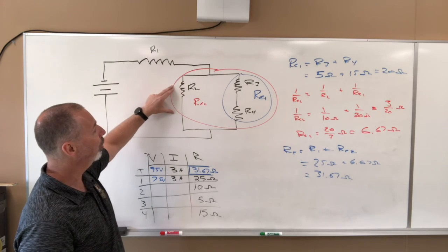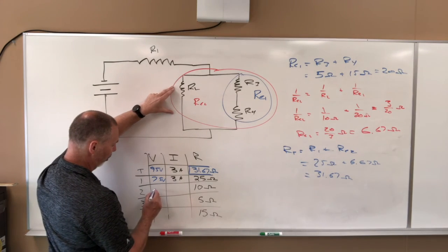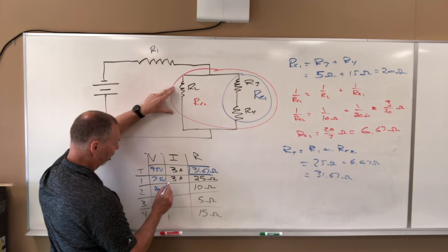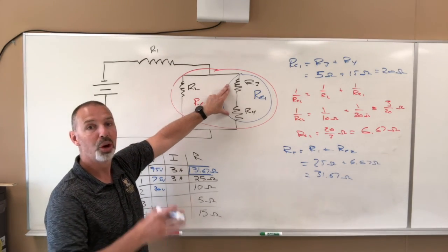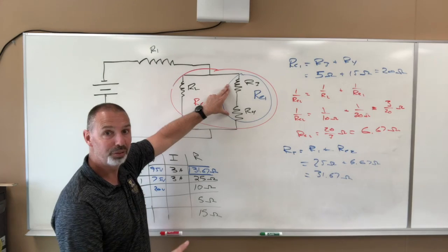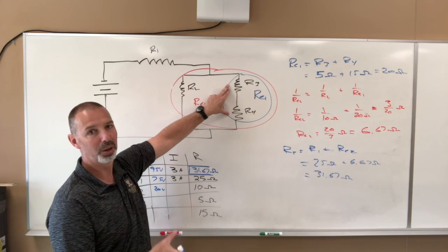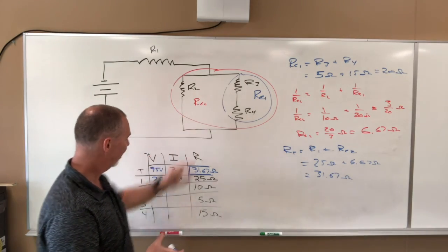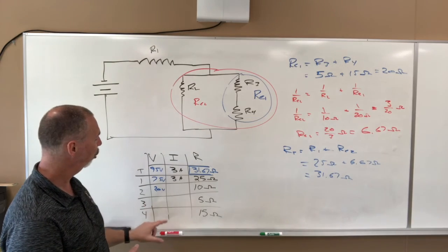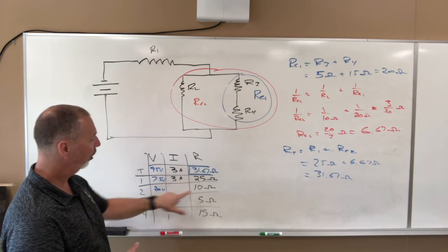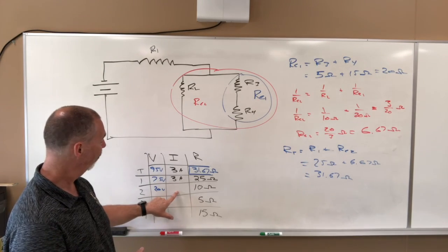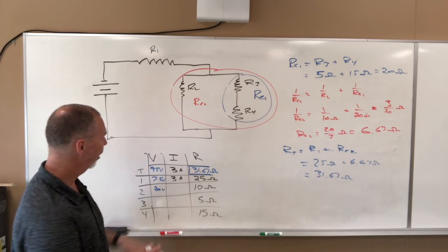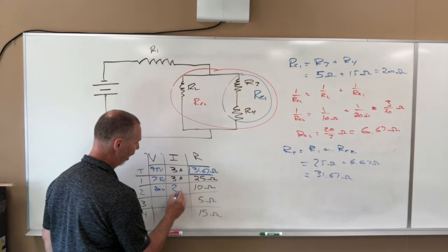So that means there's 20 volts here in R2, and R3 plus R4. So V3 plus V4 has to equal 20 volts. All right, so we can't do that yet. We've got to figure out what the combination is. But from this information here now, we can find I. I equals V over R. So V divided by R is going to leave me with 2 amps.